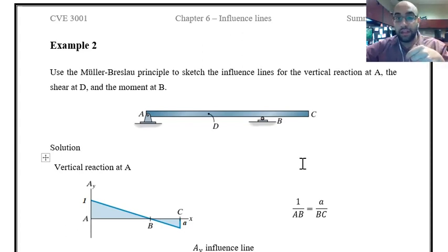Over here, we cannot have that kind of deflection because of the support. You have to have it in mind that whenever you have the support and when you are considering the bending moment influence line or bending moment restriction, you cannot have that displacement. You have to just apply the rotation.